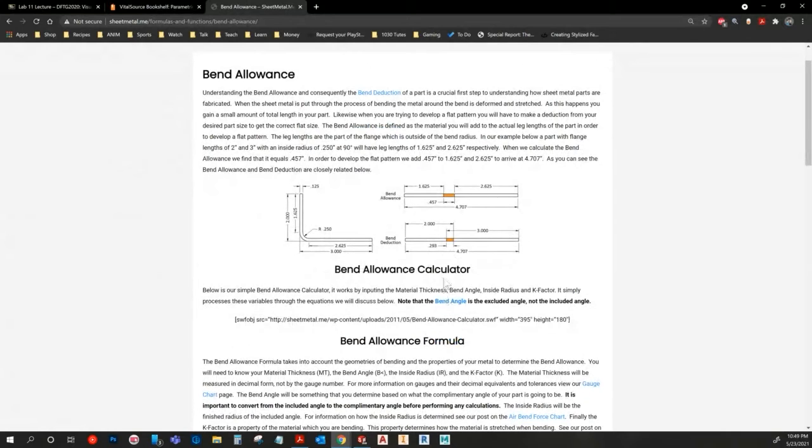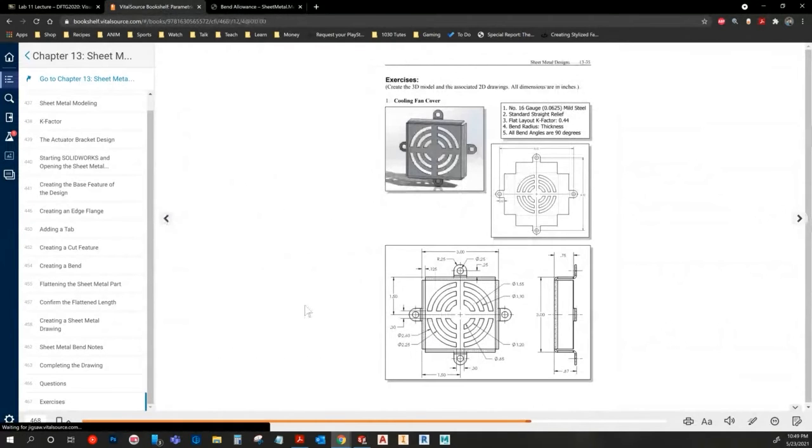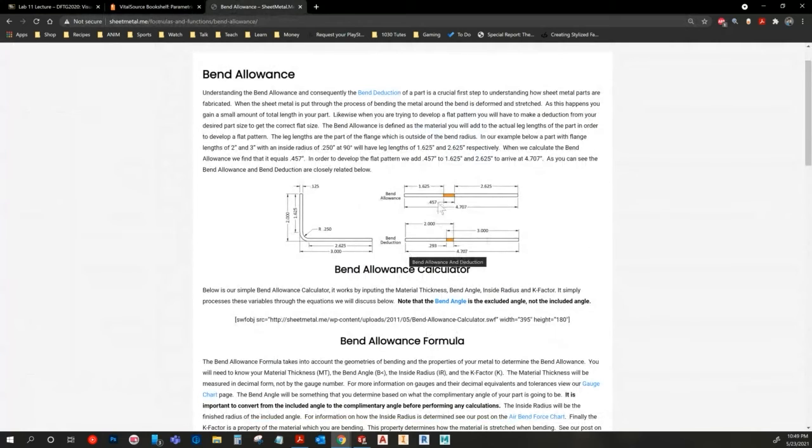And then you've got things like bend allowance, which is directly correlated when you're looking at the flat pattern, how you get the difference in values, 4.92 versus 3 plus 0.5. So 3.5 obviously doesn't equal 4.92. That's where the elongation of a part being unfolded comes in. You can really see it explained here, but basically this area stretches and compresses when you unfold it, because in order for this part to keep that same material thickness, it has to somewhat change in shape as it's grown or shrunk when it's being rolled. So there's formulas for that, and they're pretty standard.